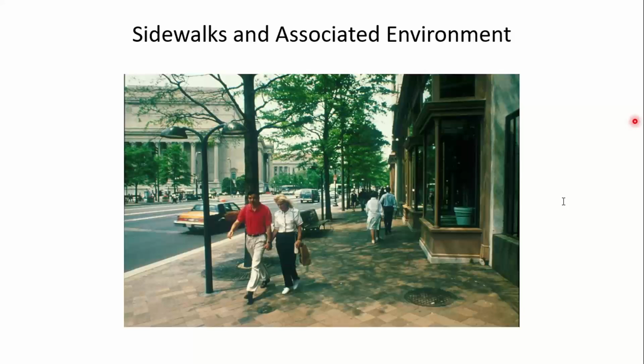And so that is one of the touted benefits of the rumble stripe with paint, is that what's on the surface of the pavement certainly probably will wear off, but you still have paint in that milled area that's protected from traffic and snowplow blades. And so the visibility lasts longer, I guess we'd say, compared to a standard or a normal painted line. Good question.